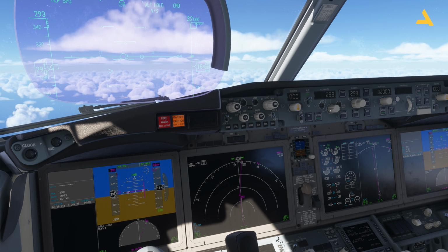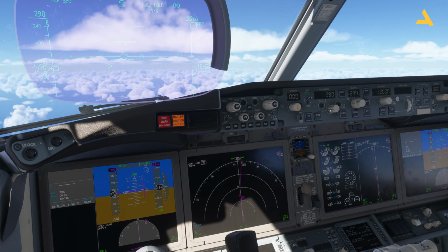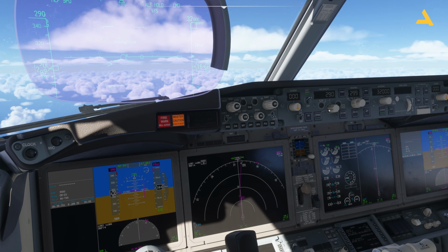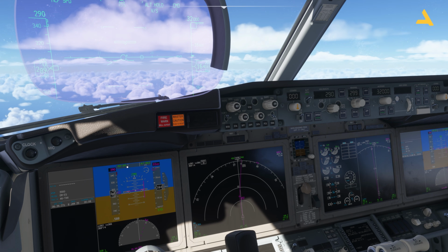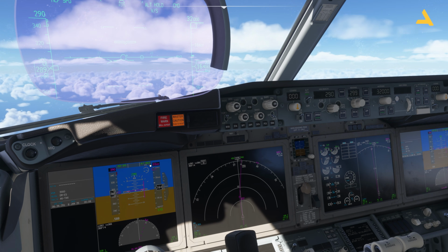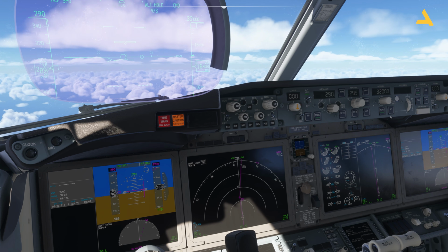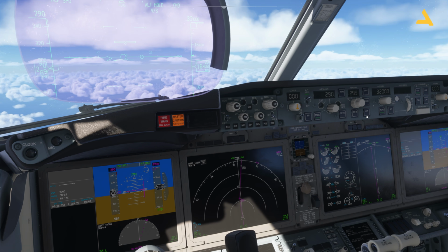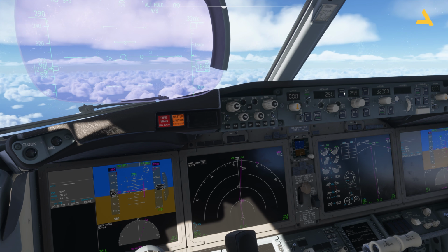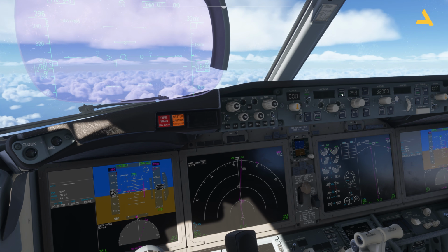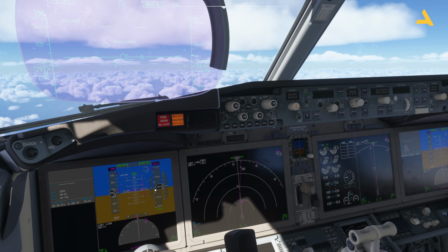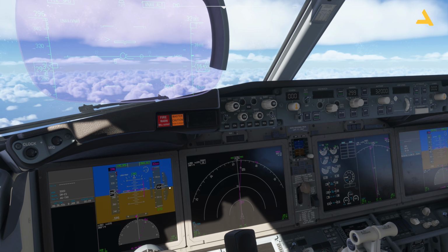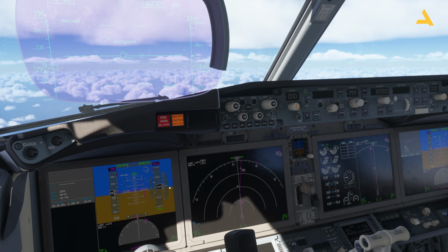Now you can see again, the speed is not controlled by the autopilot. Now you can adjust the speed, MCP speed, and altitude hold is appearing over here. Now, in order to start the climb, again, if I press this VNAV button, now the speed is controlled by the autopilot, but the climb will not start, will it?